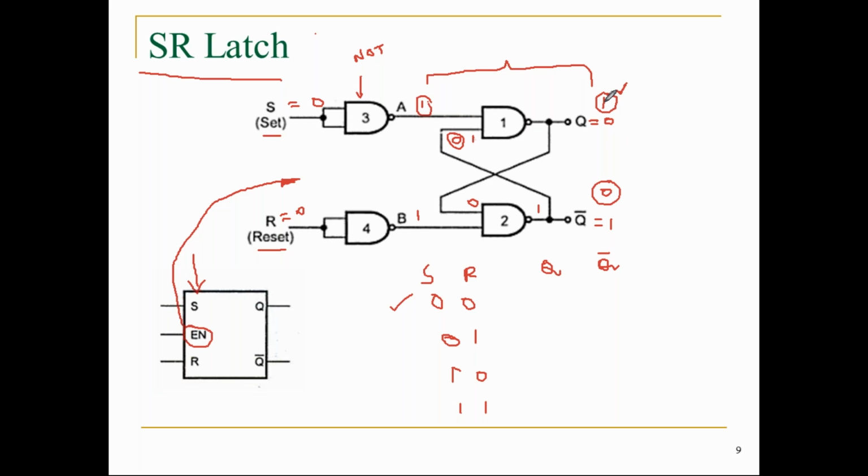So this one is again connected to here. Now you see the inputs of the second logic gate, all the inputs are 1. According to the truth table of NAND logic gates, all inputs being 1 means the output will be 0. So what is the understanding about this? Whatever assumptions I made, the same thing only appears in the output.